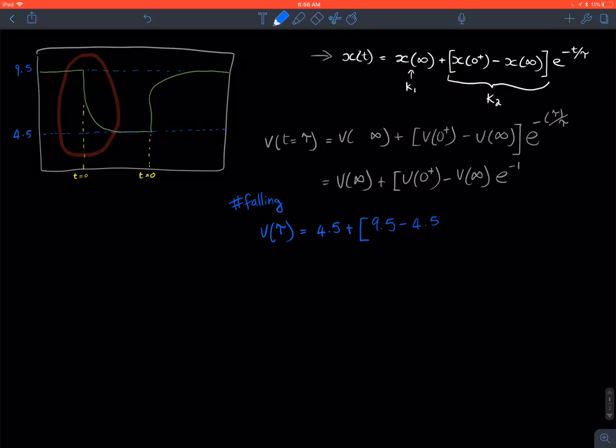And when you're looking on your oscilloscope, yours is not obviously going to be 9.5 and 4.5. It's going to be whatever the values that you measured, either with your voltmeter or on the oscilloscope, whatever values you see on your graph. And then we're going to multiply that by e to the negative 1. E to the negative 1 is like 0.3 something, but you can throw that all in your calculator, which is what I'm about to do, and you should get a value.